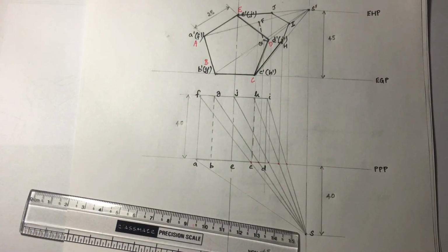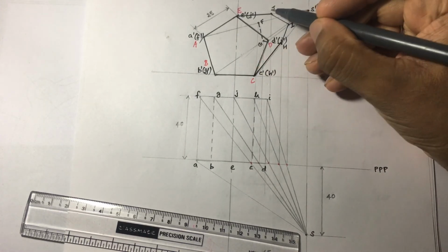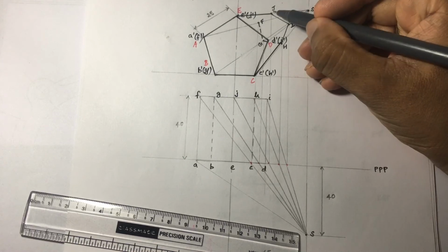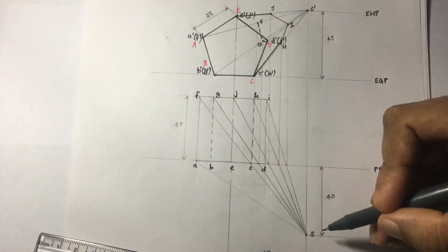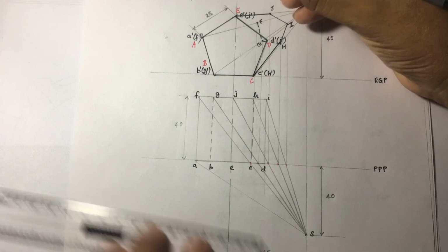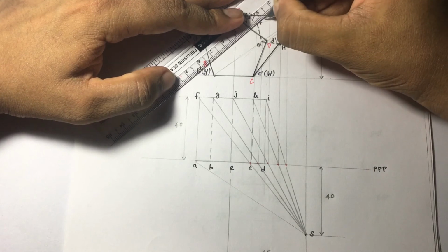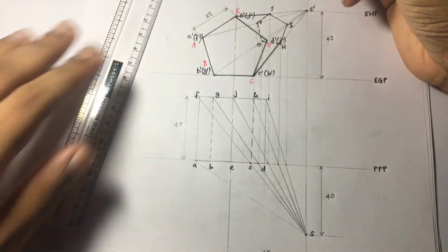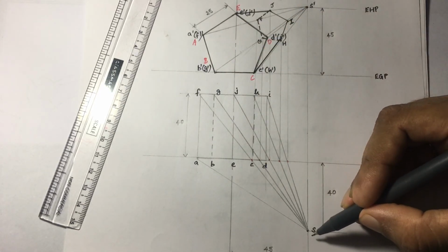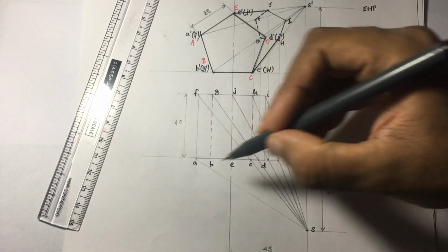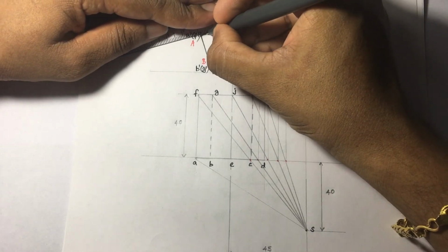Then you are having lines from F. Okay, FJ and FA. You need to look whether FJ and FA are visible. Okay, FJ is this line. This line is far away for the observer. He cannot see that. So FJ is also joined by using dotted lines. Then you are having FA. FA is this line. For an observer who is looking from here, he can see this edge and this edge. All other edges are not visible. So FA is also to be drawn by using dotted lines.